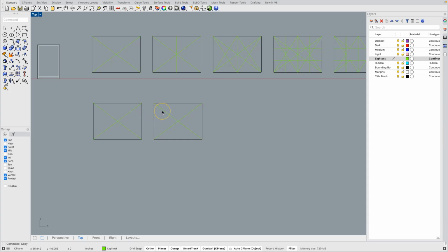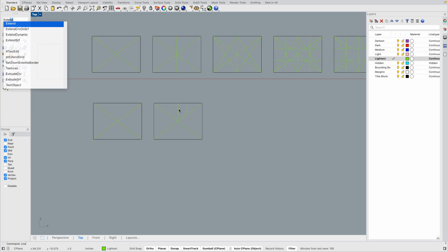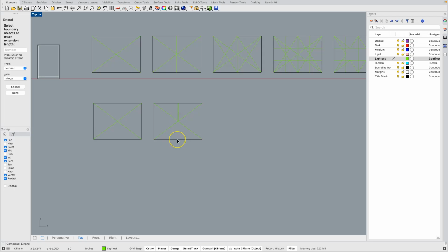between. The second thing I want to do is find this middle intersection, which bisects the page. I want the vertical, so I click on this intersection. It snapped to that, comes up to perpendicular, and now I have a short line here that I want to extend. And again, this is another tool from tutorial 2. As I extend here, it asks me for my bounding object. I want to use this as my bounding box. I hit enter, select the curve you want to extend, and I've extended this curve. I now have split the page in 2.